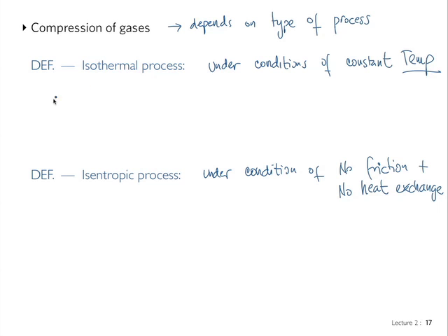In the case of the isothermal process, I said you have to bring in a little bit of thermodynamics and recall for this case the ideal gas law. And let me take a moment here to stress that it's the ideal gas law, so you don't apply it in water. The reason I mention this, although it sounds obvious, is because a student a couple of years ago did apply it in an exam to water, which caused me a tremendous amount of consternation for a moment there. So I don't want to see that again. The ideal gas law applies only to gases. Make sure you never apply it to, in that case it was, I think, a Venturi pipe with some water in it. Not a good idea. Rho equals P over RT.